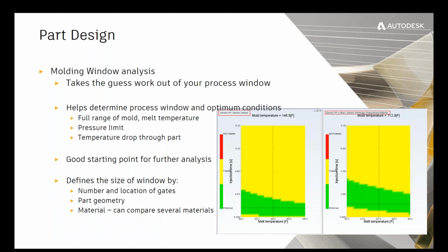Lastly, when setting up your process window and starting point, there's no need to throw darts at a dartboard, if you will. Using a molding window analysis in Moldflow allows you to quickly, within seconds, determine your process window, and also allows you to compare different process windows for different materials.